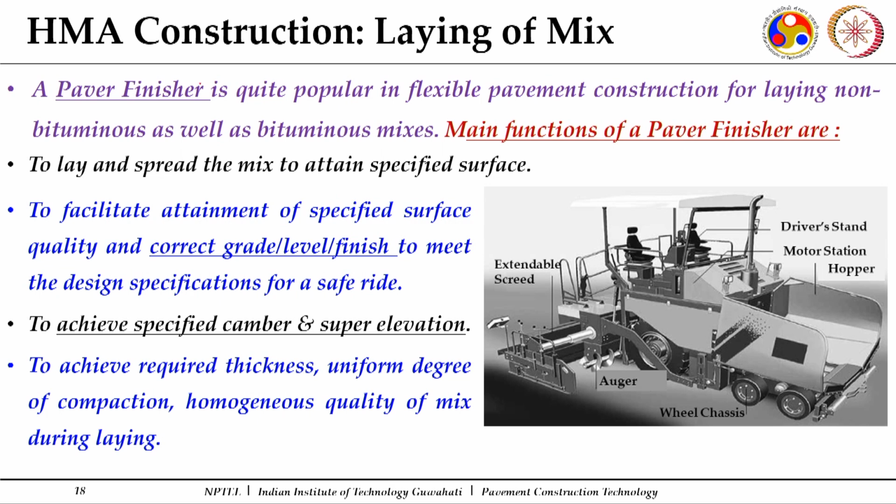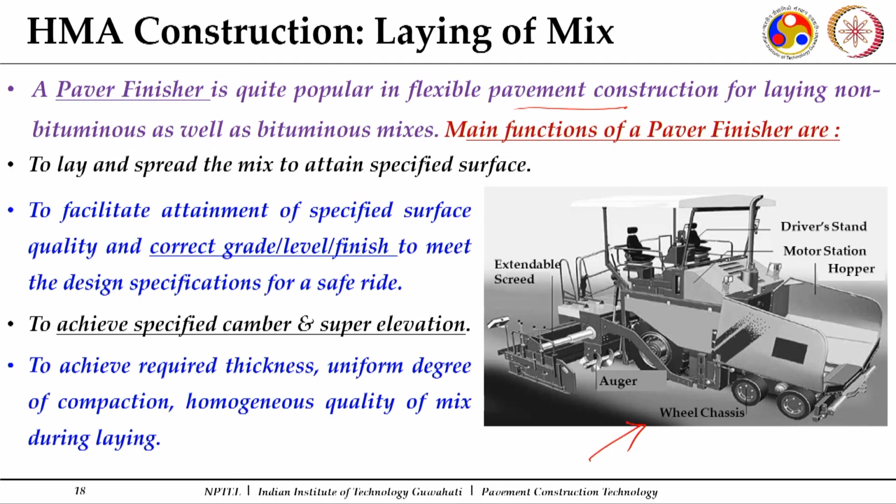This is how a paver finisher looks. This is a picture of a traditional paver finisher. It is quite popular in flexible pavement construction, specifically for bituminous bound courses, and for non-bituminous courses also. Especially with wet mix macadam, we prefer to go with these paver finishers. And for bituminous bound courses, definitely we prefer to go with these paver finishers.